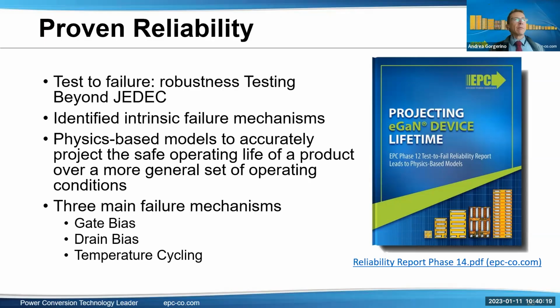It is very much related to not just how fast the device is switching, but all the parasitics that are linked to that switching. So ringing, for example, and reverse recovery is another big contributor to EMI.